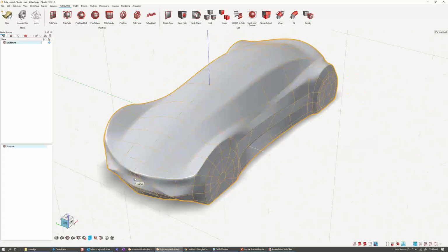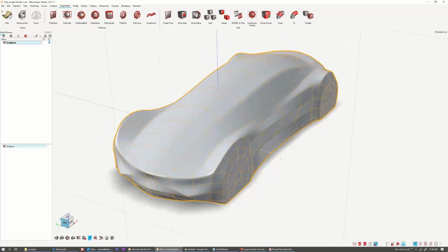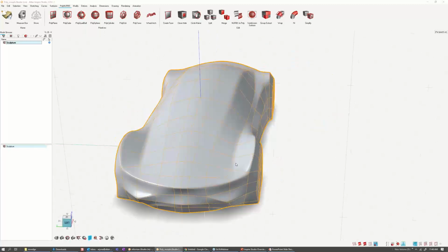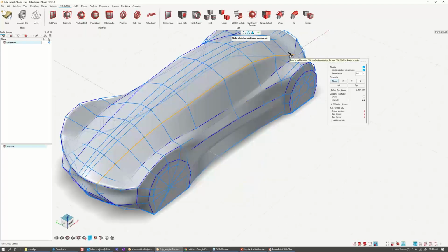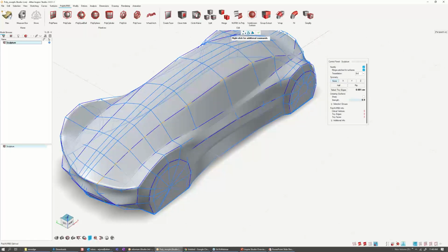As I was showing earlier, you can use some additional tools to manipulate these. For example, let's say I'm not really happy with this. I'm holding Control, Alt and selecting only this loop. It's not really looking very nice. So if I want to align this to a curve, I can go to vertices mode. All these vertices are selected. Here I can say align to a curve, and here I can give some curves.